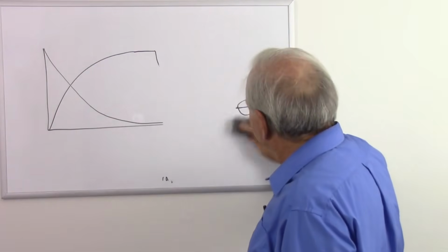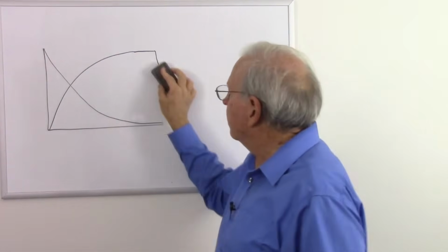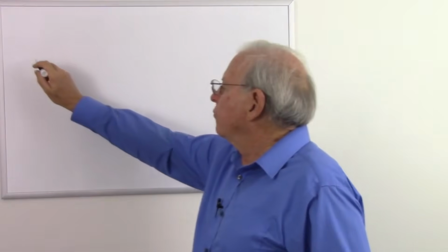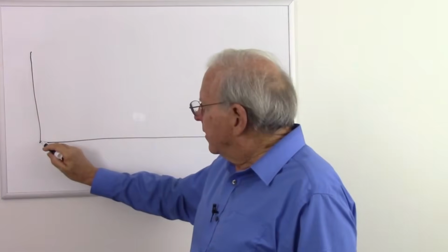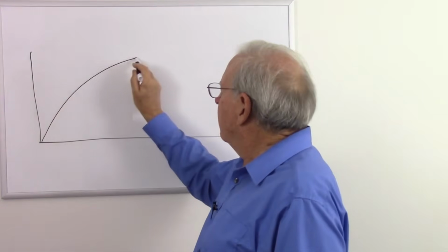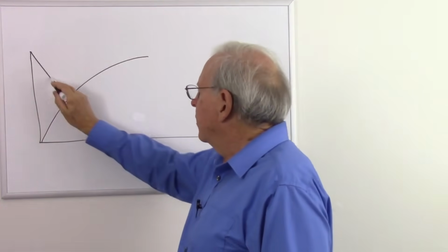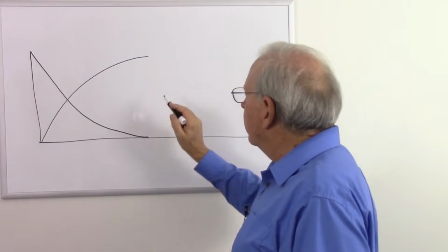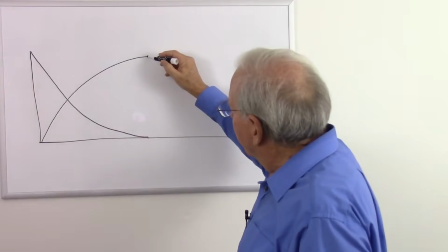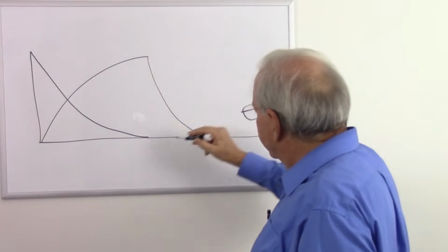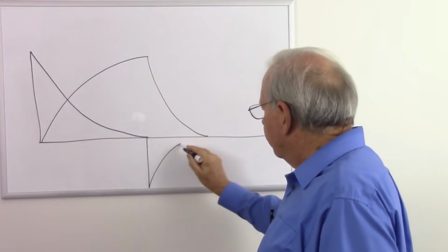Let this stay charged for a while just to point out something. I'm going to redraw this with some more space so I can demonstrate something. So let's go ahead and let that charge. We'll charge it all the way, and current's going to go down to 0. And then I'm going to flip those switches and let it discharge. So this is going to discharge. That goes down to a negative current and comes back up.